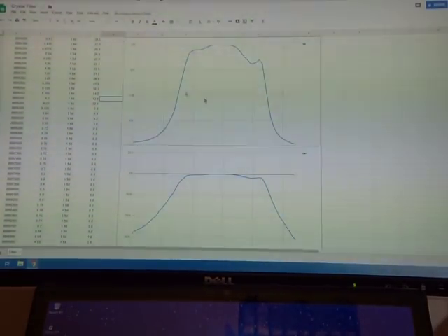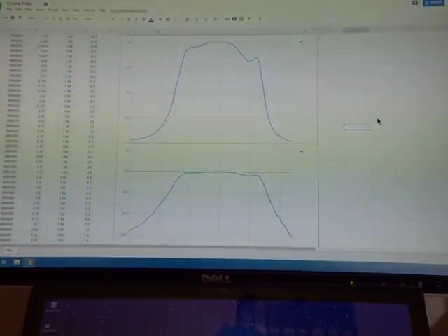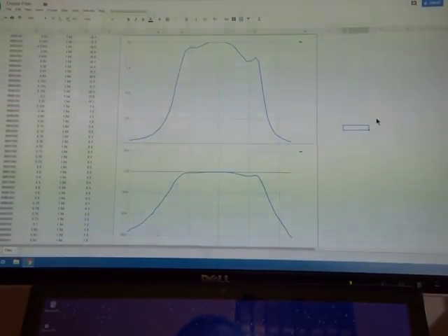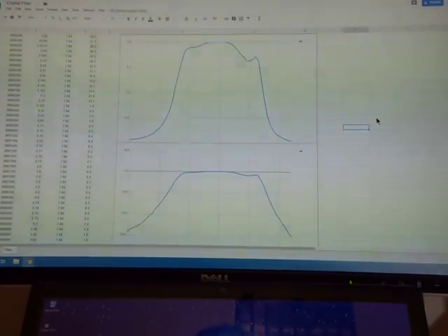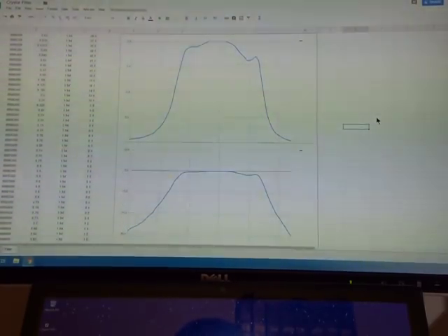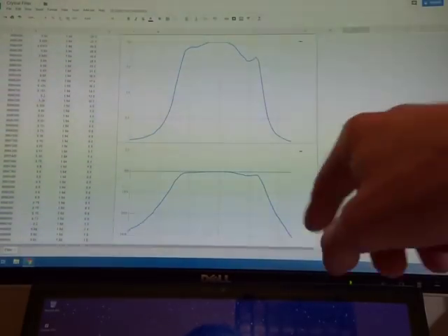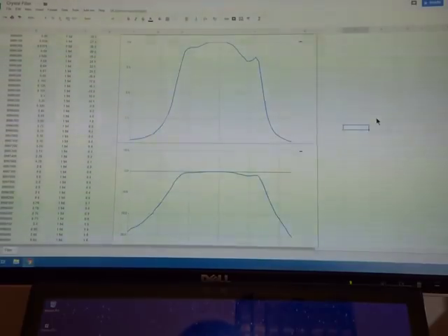So looking at the calculations there, if my numbers are correct, the minus 3 dB point comes out to be 2.75 kilohertz, and the minus 6 dB point comes out to be 2.97 kilohertz. I'm certainly open to feedback on the approach taken to measure both the passband as well as the test setup there. I really don't know if it's right or wrong. It looks about right. I guess some comments there.